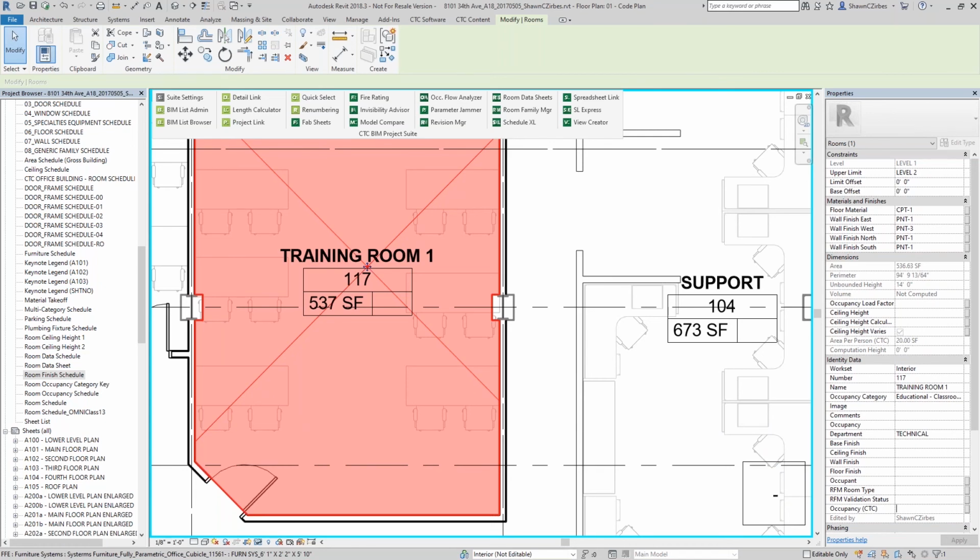I don't care if it's in a schedule, because a schedule isn't real BIM. I mean, a schedule can show me data, that's great, but if the data only exists there and not on the room element, then nobody else, none of my consultants, I can't export the data. It's not usable by any other team members other than whoever is live in this Revit model.